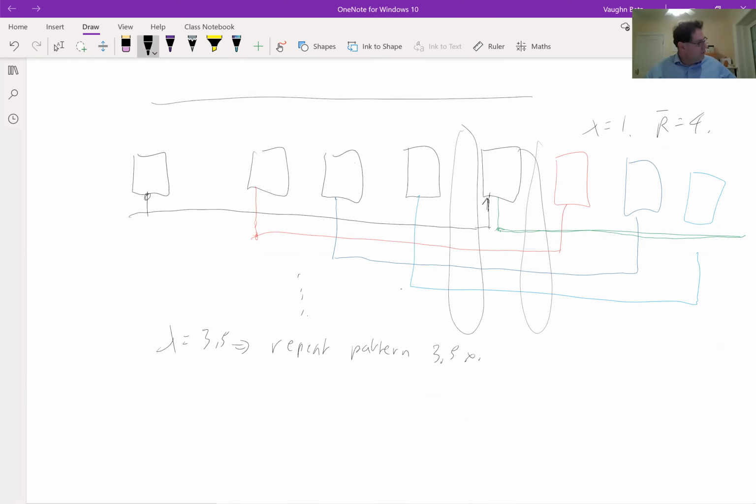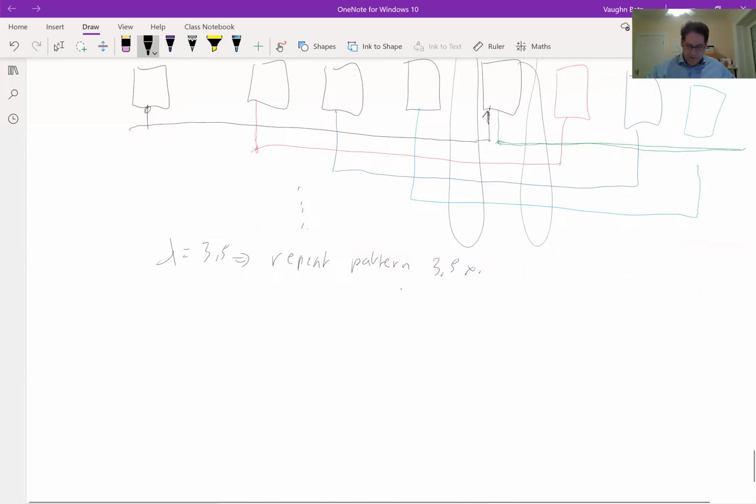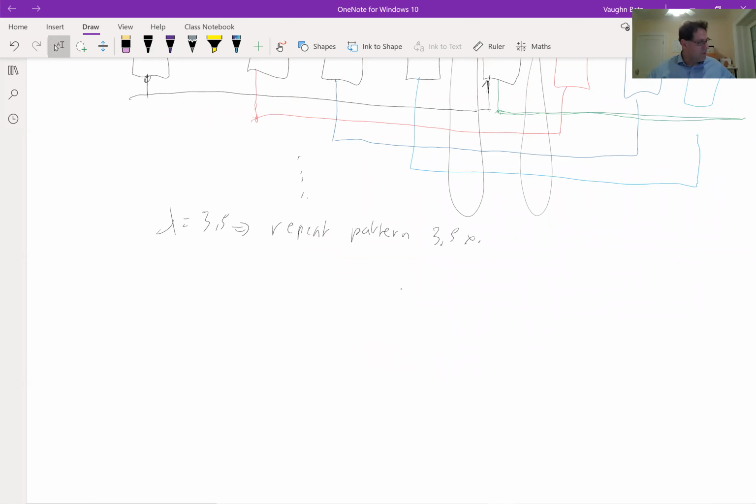So does this make sense? This has sometimes been called the Ohm's law of FPGA architecture. So if you don't understand this, let me know. This is basically how locality, R bar, and the number of inputs you need to get to every block interact with the channel width. So this is an important basic trade-off rule that you want to understand. I'm going to take silence as that you get it, which again is maybe dangerous, but we're going to just keep going.